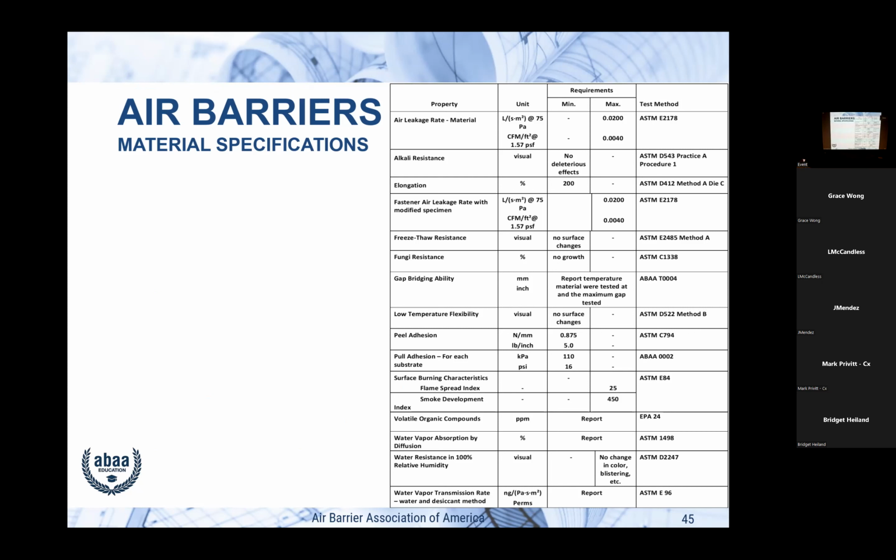We did a whole research on 5,000 different reports of pull adhesion being done in the field. And we expected different materials would have different rates. And we expected the same material on different substrates would have different rates. We were really surprised that that difference was very little. The range from the worst, and we got some outliers, but the range was basically between 20 and 23 PSI. Doesn't matter the material, doesn't matter the substrate. And that surprised us. And we really expected gypsum to come in around 4 or 5 PSI before it came apart. And it didn't. It was around, if we do the average, about 21 PSI.